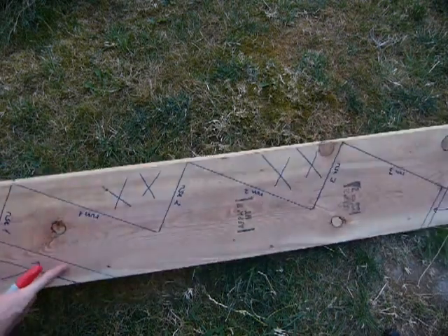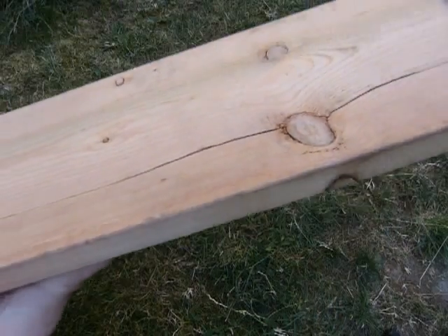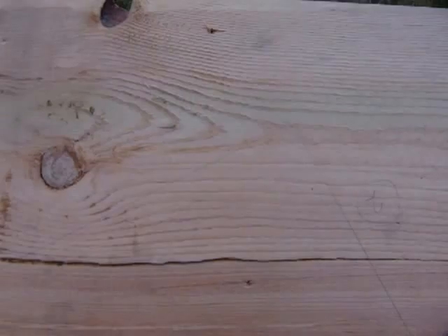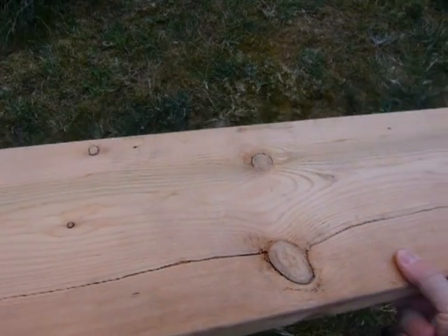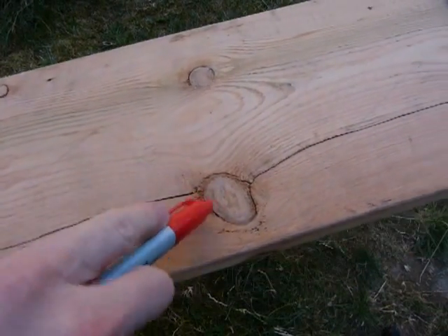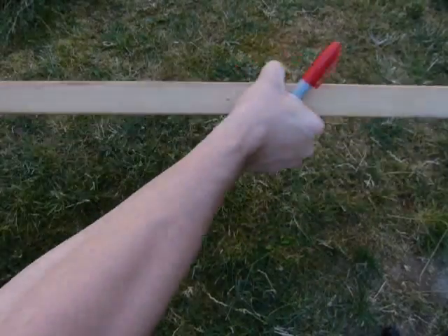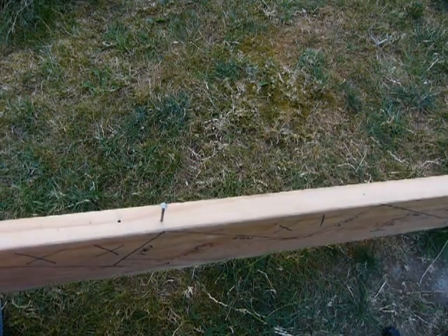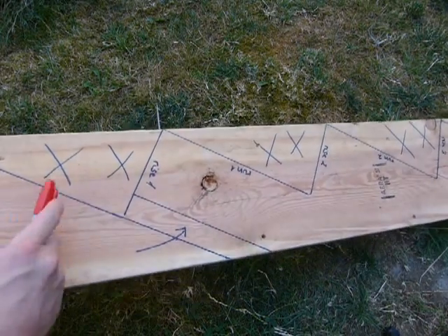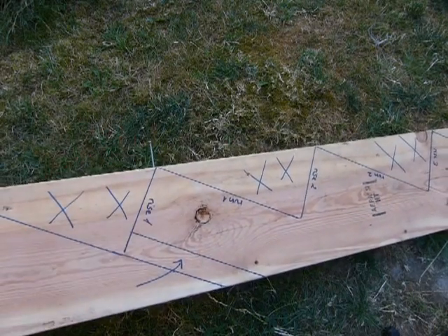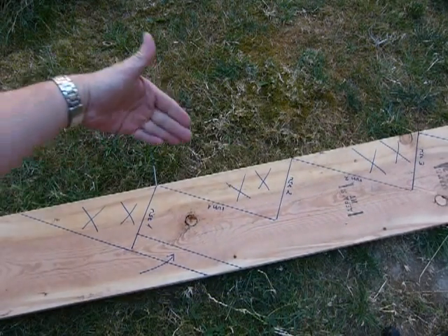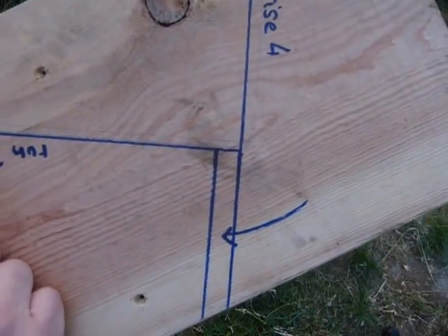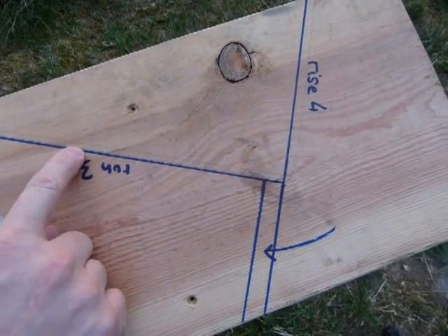But what happened here? Let's go back a little bit to the penciled in version. Yep, there are some pencil marks that are barely visible. So this had to be shifted because of this knot, 2 inches forward. For that purpose, I moved this reference point forward a little bit and made my first run and rise there, and then my second, my third, and my fourth. If you look closely, by the time I got to the fourth, you can see my pencil line there.